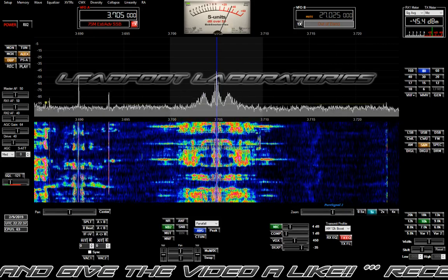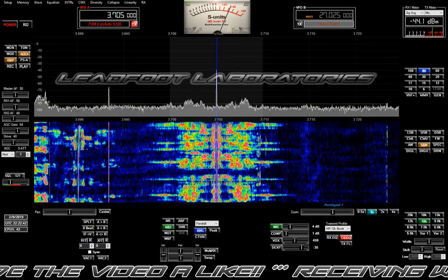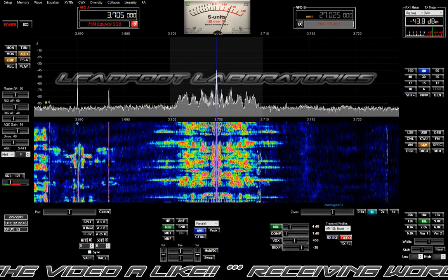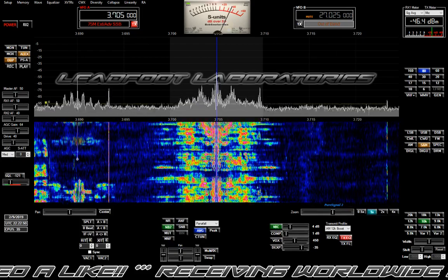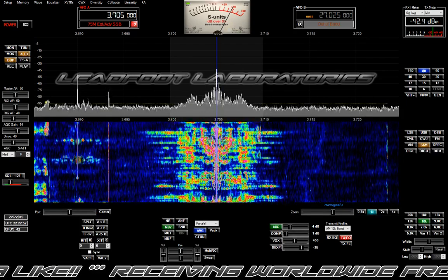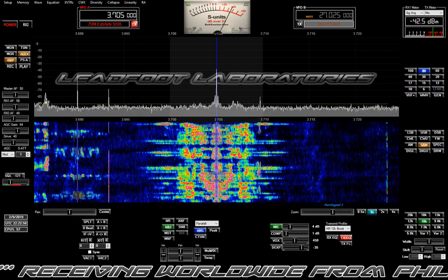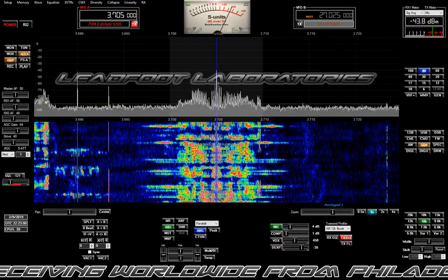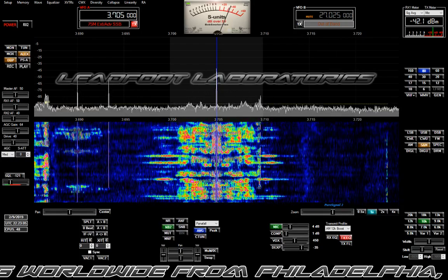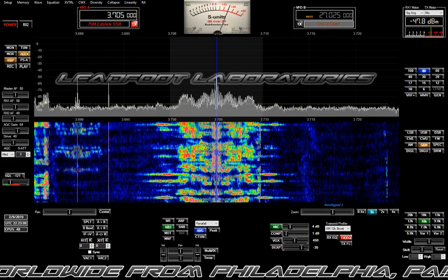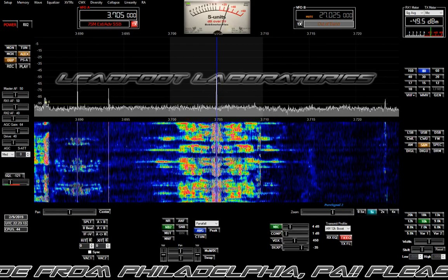And then the other thing is, too, I remember reading just a couple of years ago, talking about the record production business. I would certainly agree, Frank, that the technical quality of the hardware that's out there now is the best it's ever been. Nobody's going to dispute that. In terms of the linearity of mic preamps, bandwidth, sampling rates that are available for recording in the digital domain, 24-bit, 192 kilohertz sampling. I mean, it's literally a transparent recording medium nowadays.